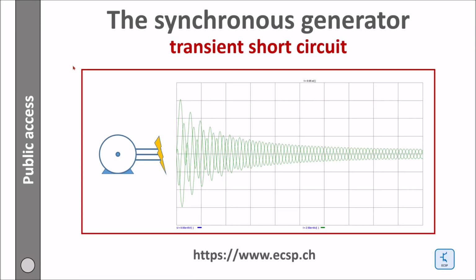Here is the user's guide for the transient sub-transient model of a synchronous generator. The transient model is implemented in a three-phase star-grounded source model. As an example, I draft a very simple test circuit consisting of a three-phase source and a three-phase breaker.